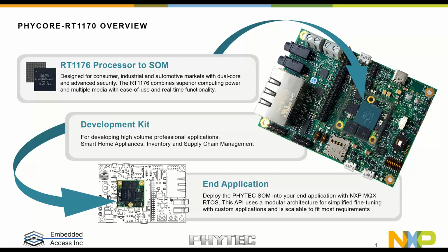If you're not familiar with the concept of a SOM, PHYTEC builds a printed circuit board assembly around the RT1170. And we include other important components such as the DDR, NOR flash, and RTC, components which are necessary to complete your embedded system. One side of the module has connectors allowing you to plug the SOM into the carrier board that is unique to your application. So everyone's carrier board is going to be a little different based on the IOs that you need. That's how embedded systems work.